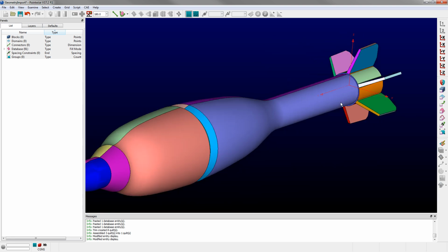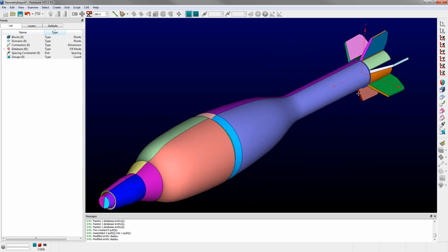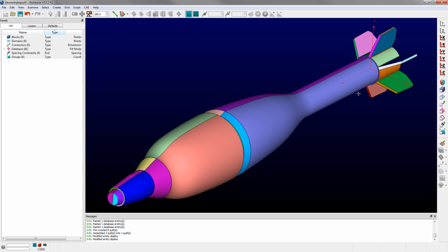Now, I didn't have to do some of those steps, right? It depends on how much of the geometry you actually want to recover with the mesh. But in this case, I want to mesh over some of those small features. So I'm, again, selectively defeaturing some of the geometry. All right. Okay, I'm set. I'm ready to go. I can actually mesh this thing at this point because I know it's a watertight model. I've got my quilts all set up.